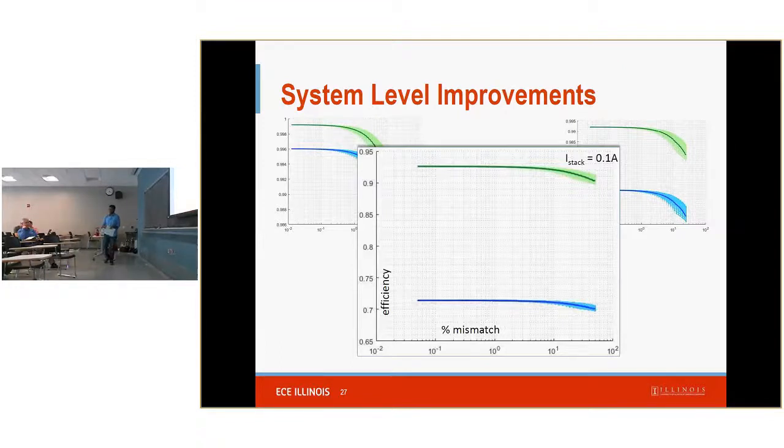For DPP with servers, you can use isolation converters, but this is not that. Yes, this has to be non-isolated. So is that okay for a core to be non-isolated? Usually very high dynamic performance is needed for core voltage regulation. You can see from Intel's FIVR papers that they have about an 80 megahertz bandwidth, which enables load current tracking on the nanosecond scale. With isolated converters, it's going to be much more difficult to maintain such a good bandwidth.